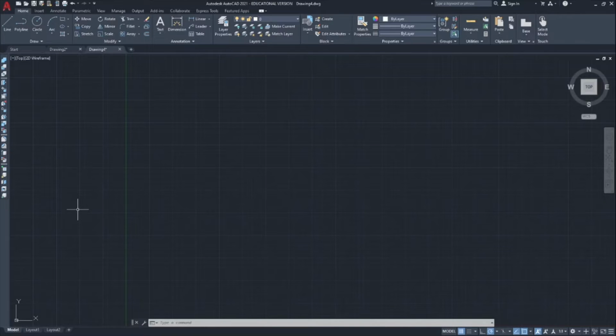Now, if we wanted to float this instead, we would go dash toolbar. So subtract symbol toolbar, hit enter. Again, typing in solid underscore editing. Hitting enter. Now what if we wanted this to float around instead? So I've gone over docking. Let's click the float option. Now let's just say we choose, I don't know, let's go 100, 100 as my new position. Really doesn't matter because you're going to drag it wherever you want it anyways.